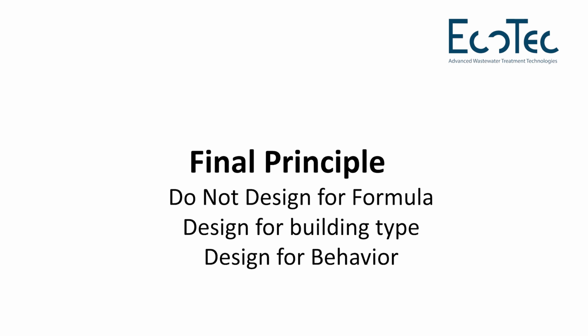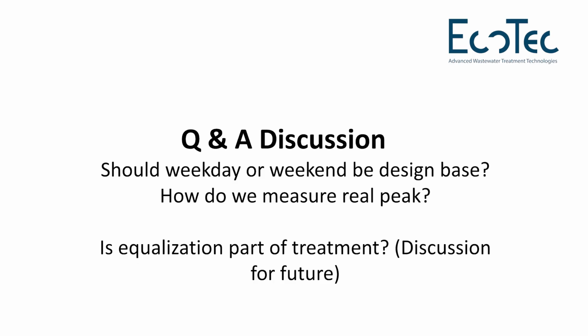Finally, what we have learned here: let's not design using formula, but consider the type of building and the behavior pattern of the people that use the building. Having learned something about peak factors, let's ask ourselves a few questions. For a mall, should we design the sewage treatment plant with a weekday peak factor or a weekend peak factor? How do we even measure real peak?